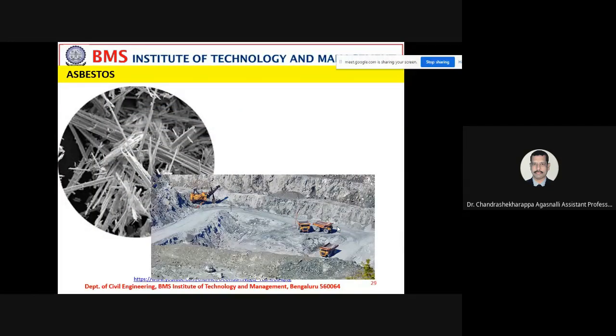It's white. See here, you can see this. This is white, like a thread. You can easily find how it looks. And to some extent it looks dangerous when it enters the lungs. You need to take a lot of care, because it has very thread-like structures, it's rich in magnesium and alumina, and it's a health hazard. So you should not be exposed to much of this.